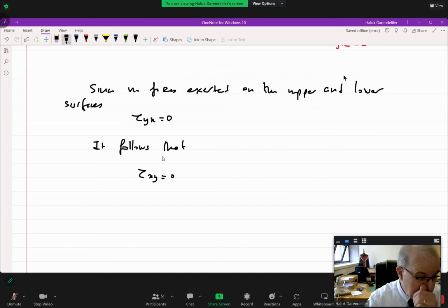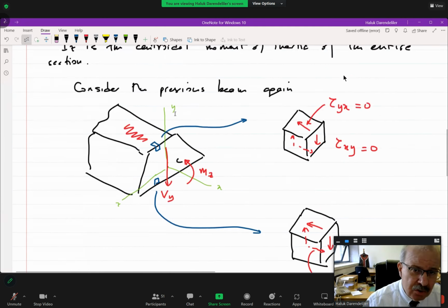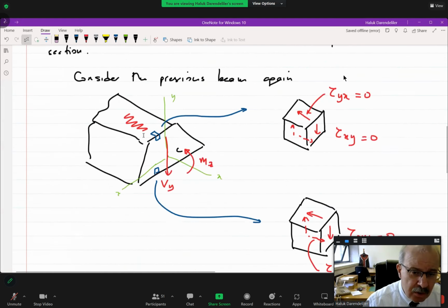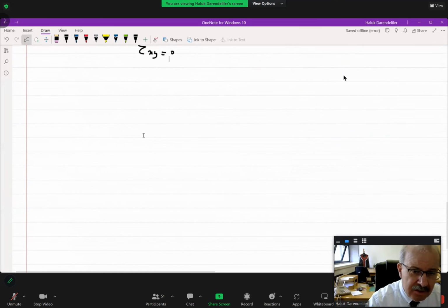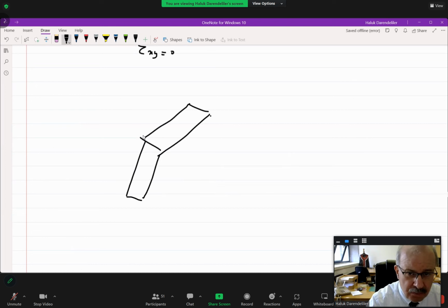Okay. Now look, why have we written average in this equation? It is because of this. Let's take that slab once more, which we started with. On this slab, we have a shear force Vx, and we obtain the shear stress as VQ over IT. Now look, the shear stress has such a distribution on the cross section.